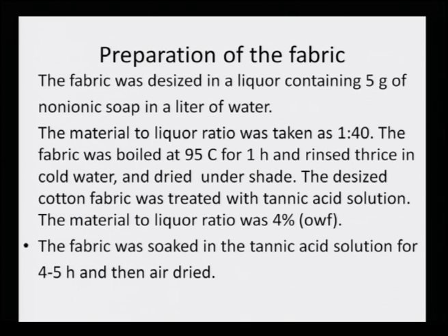Time and again, when we have spoken about natural dyeing, I have told you that this particular step cannot be avoided, for the simple reason that cotton does not have enough free hydroxy groups to chelate with the metal or with the dye or the metal chelated dye. So, this tannic acid treatment offers linking groups or attachment groups ready to attach the chelated dye. That is the role of tannic acid.